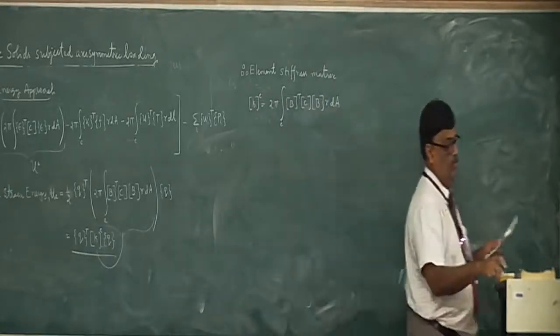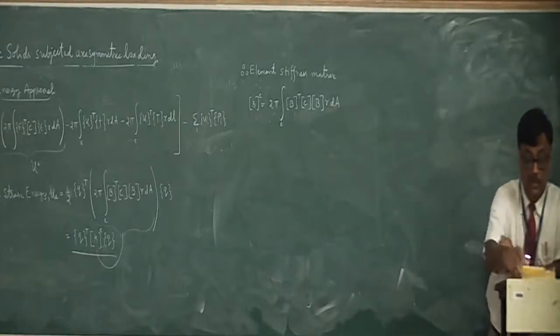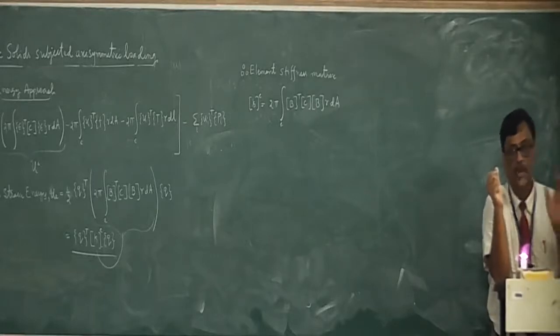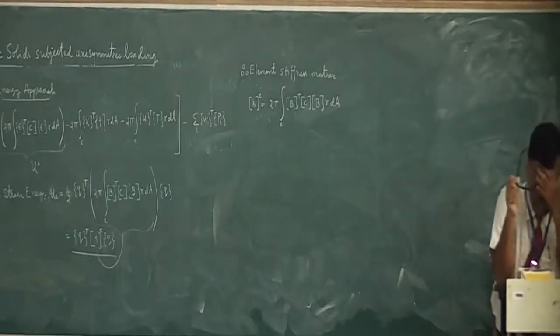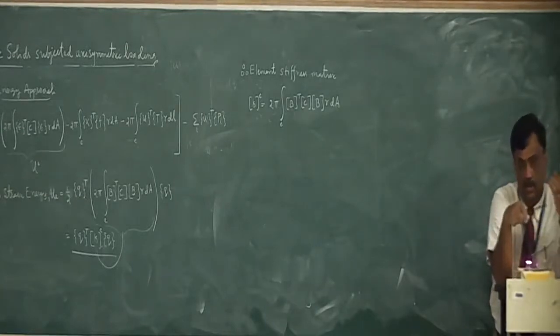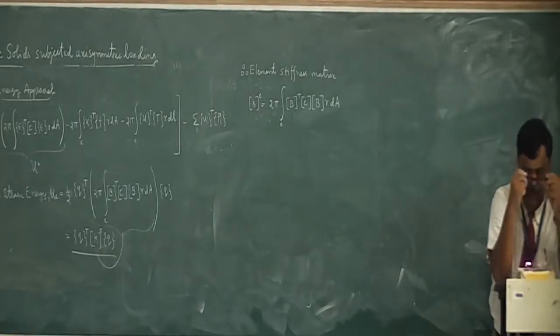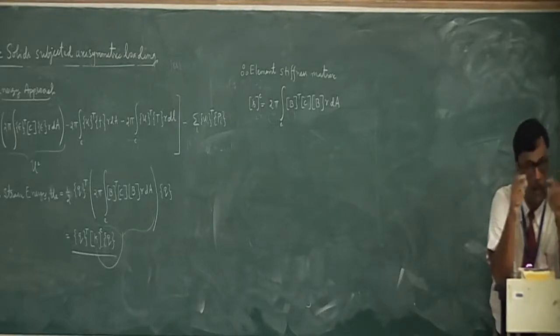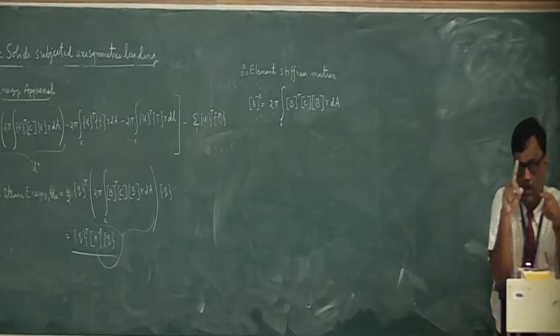Yeah, this is the most interesting part of what you have seen. See, if you look at the B part, that is the strain displacement matrix, when you see the fourth column of that, you have seen, it is containing terms like N1 upon R, N2 upon R, N3 upon R, and all that. So that means we need to integrate this equation at a given R. So additionally, this R, where exactly is that value of R? It is neither at R1 nor R2 nor R3. That R needs to be integrated with respect to a certain value.